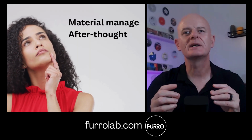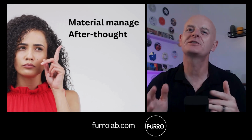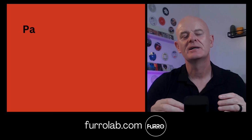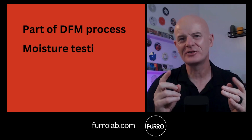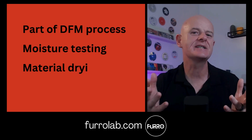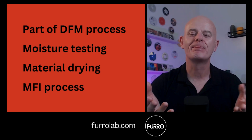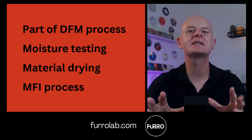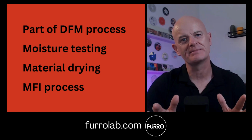Material management is often an afterthought, or maybe it's part of the root cause analysis when something breaks and crashes. Plan this upfront. Make it part of your DFM process. Things like moisture testing, material drying, MFI process. All this needs to be in place and it needs to be a part of the daily process.